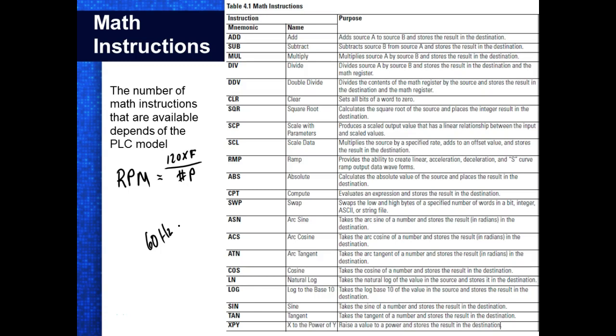So technically it looks like, you've got a ceiling fan, anybody got a ceiling fan? To shift speeds, you're switching the number of poles, how they magnet, how they wire the stator. Usually there's 3 speeds, right? You have a high speed, a medium speed, and low speed. Look at that switch. It's got 4 wires. One of them's a power wire, and the other 3 are sending different voltages to the windings on the motor.